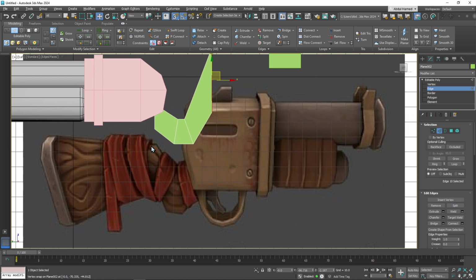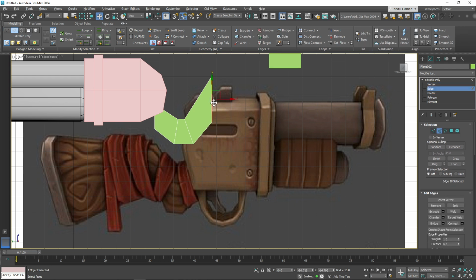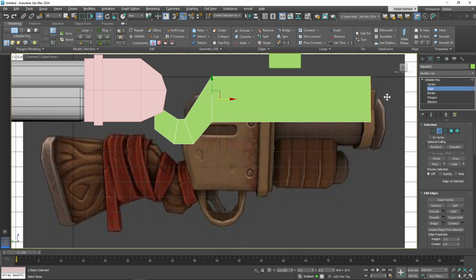So right now, if you can see, this is at the lower half. We can see the snapping here. This is being activated by S. It must have been activated by mistake. So let's deselect it. Let's move this a bit down. Switch to vertices and switch this up. Back to edge, shift, and extrude out.